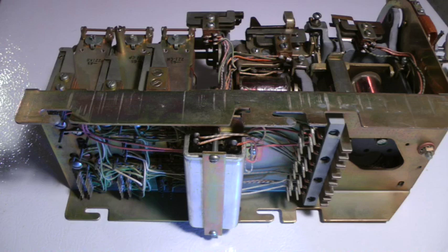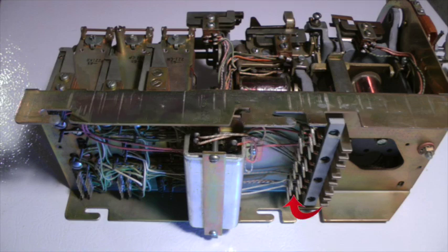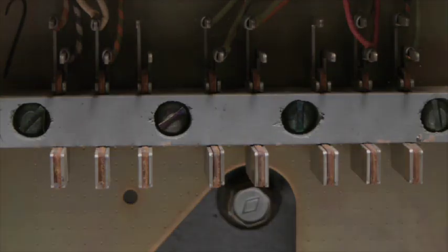Located below the A network is another assembly. This assembly, which consists of these terminating pins, a wooden mounting block, and these sets of prongs, is called the line finder plug. There are 16 prongs arranged in 8 pairs, with an insulator separating each prong of a pair. The wiring on the plug's terminating pins connects to internal line finder circuitry.